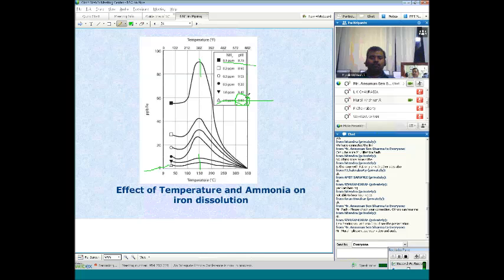Now that is the only remedy so far as flow accelerated corrosion is concerned. Change the cycle chemistry with ammonia dosing, increase the system pH to around 9.2 to 9.6, and that includes the feed water pH. Usually the feed water pH is most commonly in the range of around 8.6, 8.8, 8.9, right? If you are having problems with FAC, you have to increase that feed water pH to around 9.2 plus. That is the only solution to FAC.